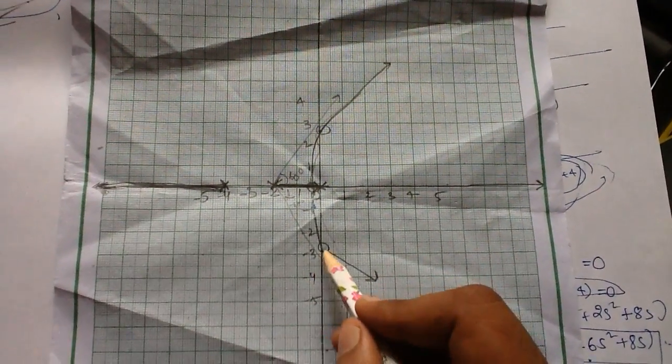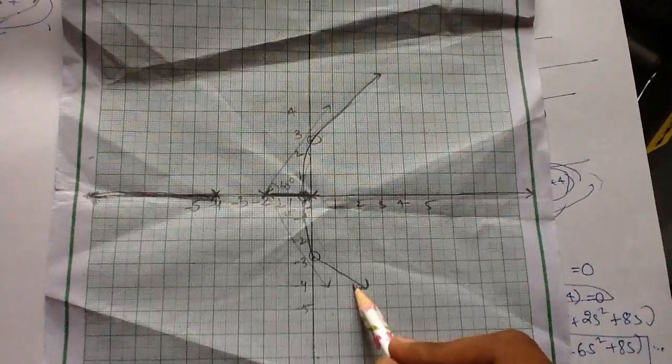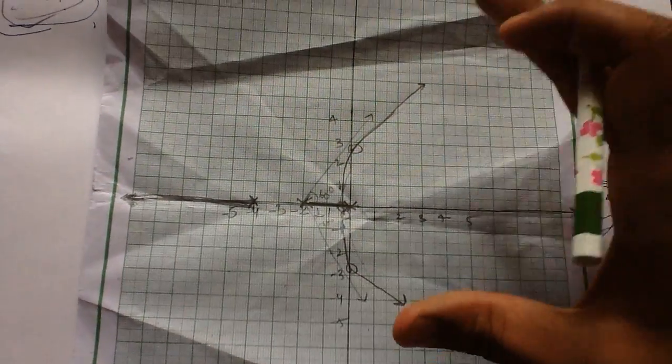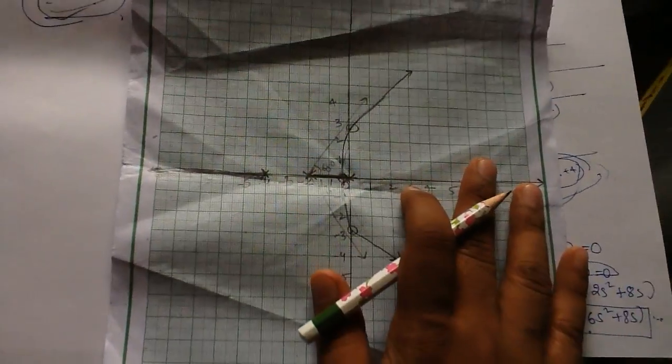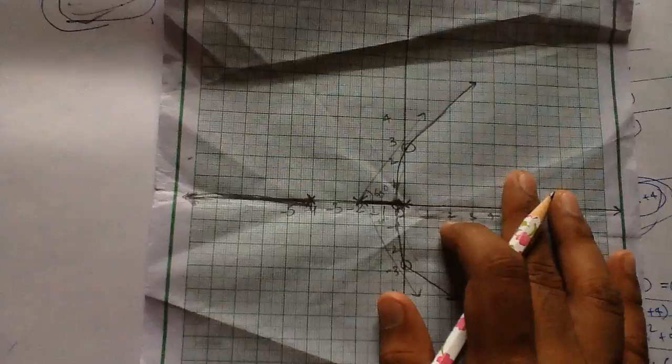And remember, draw perfectly and see that you don't get more curves and all, because the root locus is always symmetric along the real axis. So this is how you draw the root locus when you have no complex zeros and poles. For complex zeros and poles, I'll be making another video.